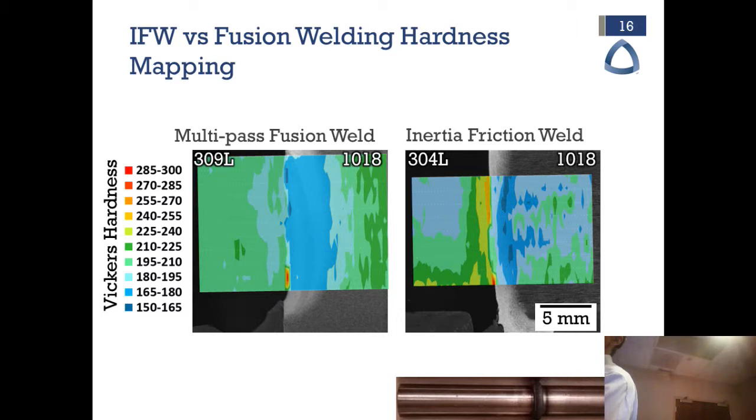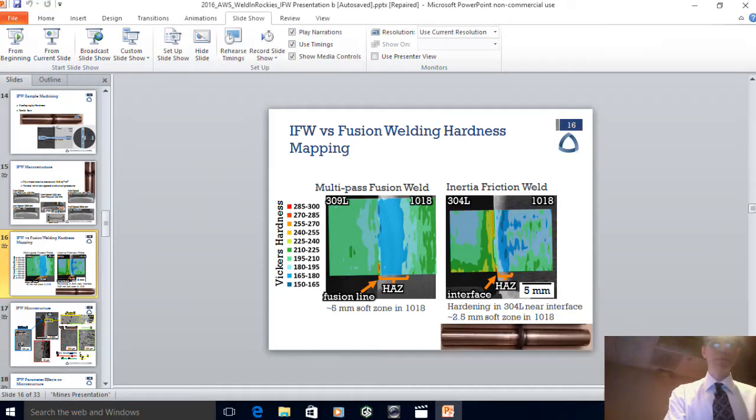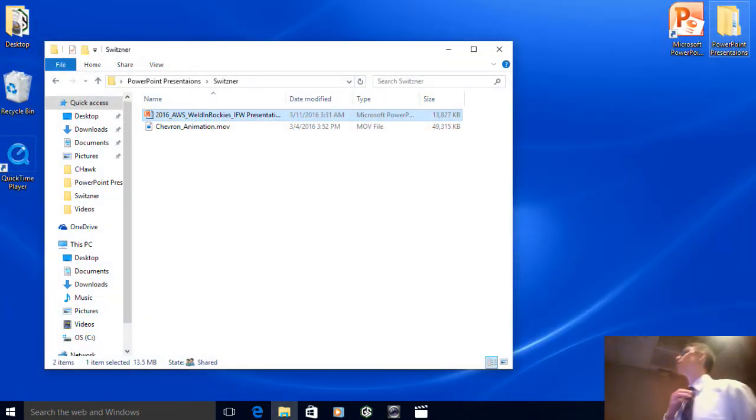Okay, well, is there an ASTM classification for the 1018 steel? Oh, probably. For example, in ASTM you have the A something, 836 is mild steel. Right. But there's a distinction: the AISI grade, for example, is more based on chemical composition, while with ASTM, many of those grades are based on mechanical performance or properties.